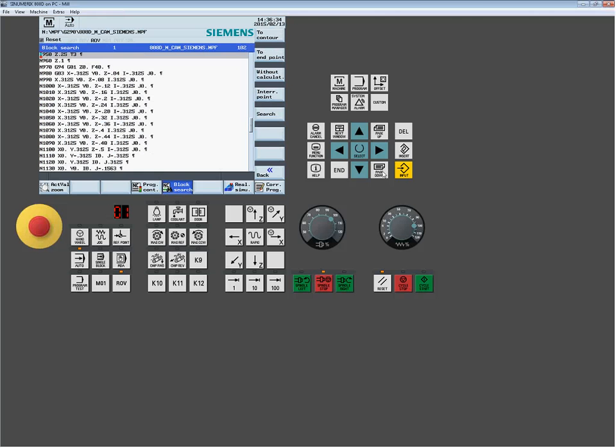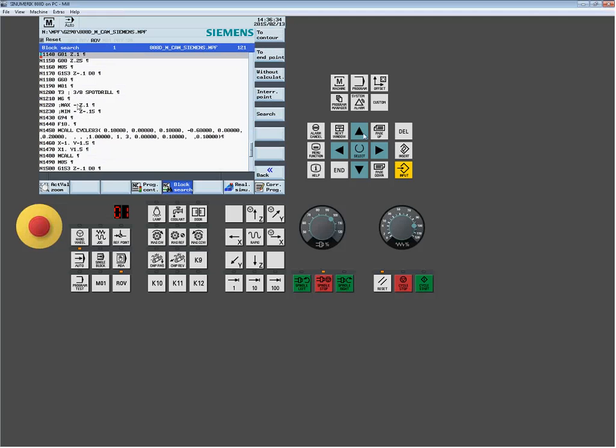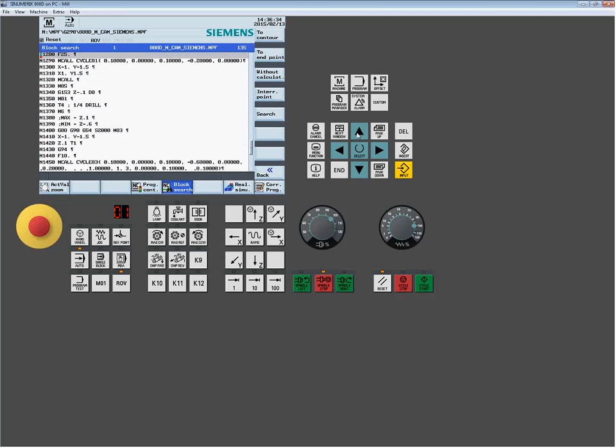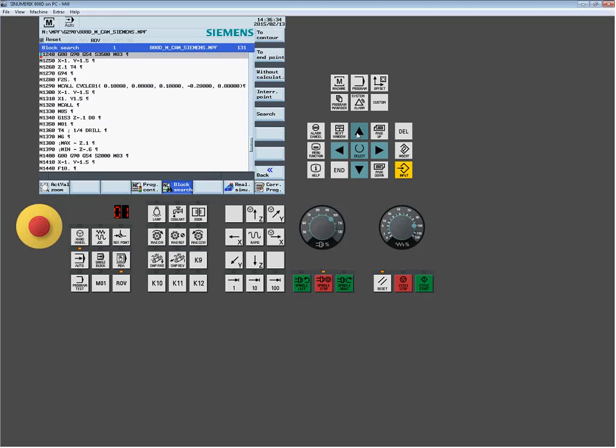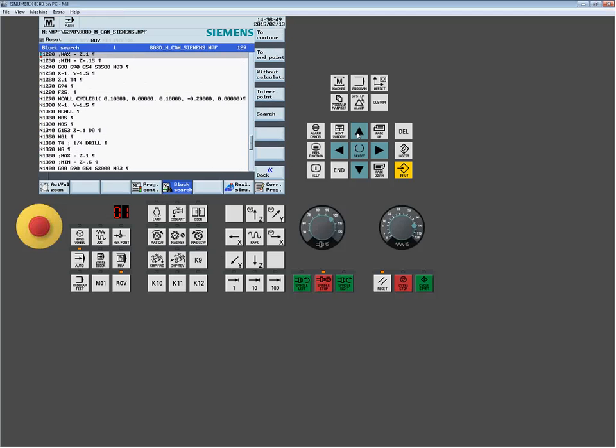Work coordinate, whatever work coordinate you want to use. Now, I can use this GOTO, and we'll use this in a little bit to jump around. We talked about that one. Then I do a tool change, load my tool. Now, you see, I like to put this D1. This is what tells the system what offset I want to load. You don't have to.